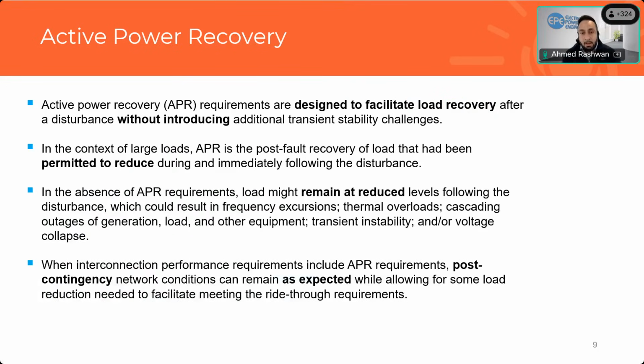As noted before, active power recovery is something we want to dive into a little bit more. And it's actually an enabler for these load facilities to ride through. So those ride-through curves inherently are very challenging for the large load facilities to meet without introducing some level of load management. And what we've been describing here is that APR is kind of a post-fault recovery of the load that's been permitted to reduce during and immediately following a disturbance. So in order to facilitate ride-through, allowing the load to reduce its consumption.